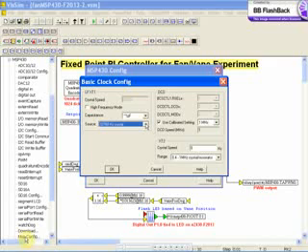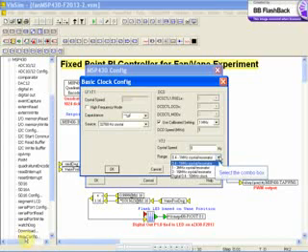Each F2000 series MSP has a calibrated DCO and BCS register setting for specific frequencies stored in information segment A. A second external oscillator can be used in a 400,000 Hz to 16 MHz range. Leave the value 0 if you are not using this one.